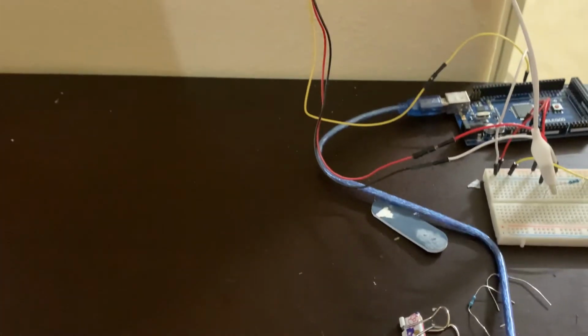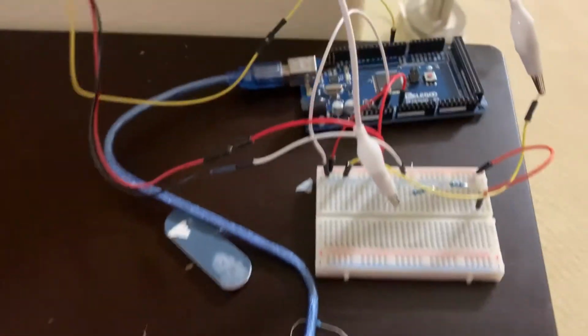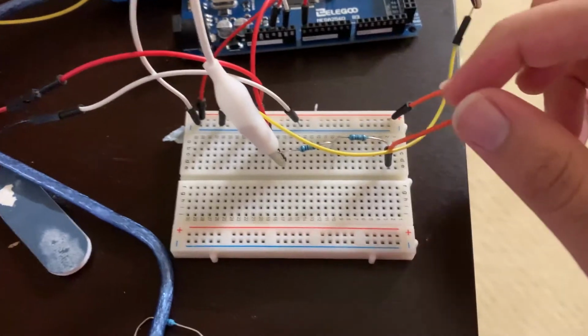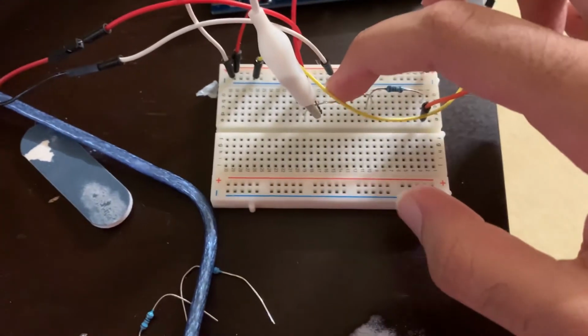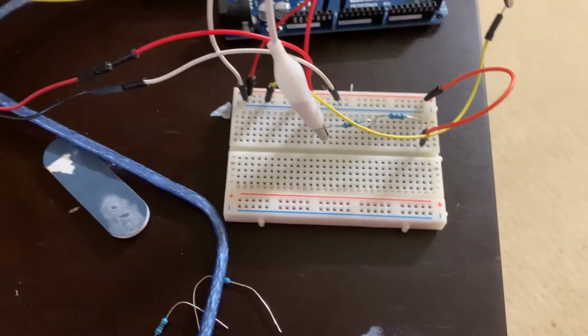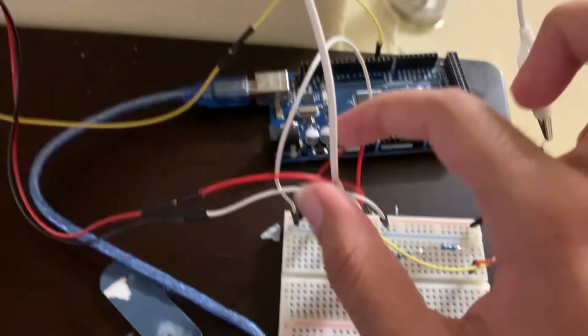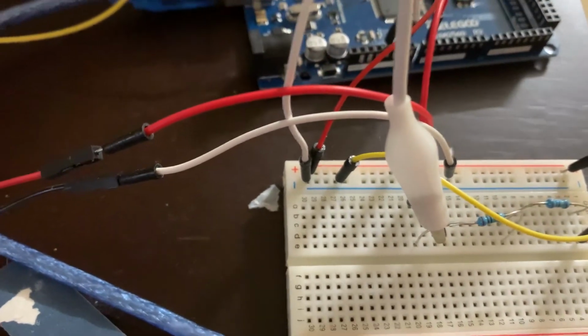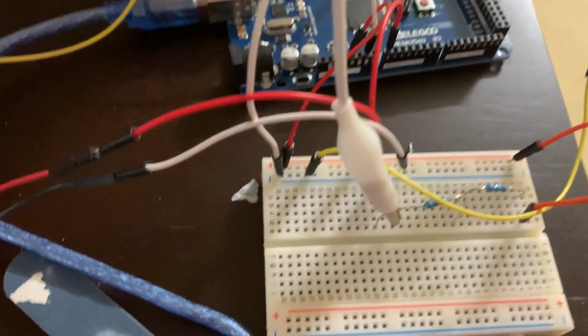I took away my laptop, but it would be plugged in using this cable to the Arduino. The laptop is what provides 5 volts input to the Arduino, which the Arduino then transfers to this breadboard using this red wire. This wire is connected to these 2 resistors, both of which are 1 million ohms, so they add up to 2 million ohms. And then I have a jumper running up here to my photoresistor. Then I have another jumper going back down here into this yellow wire, which goes into our ground or our negative terminal of our Arduino.